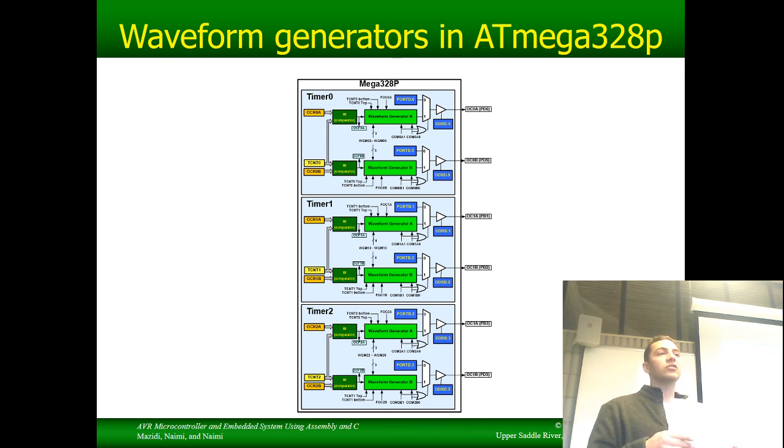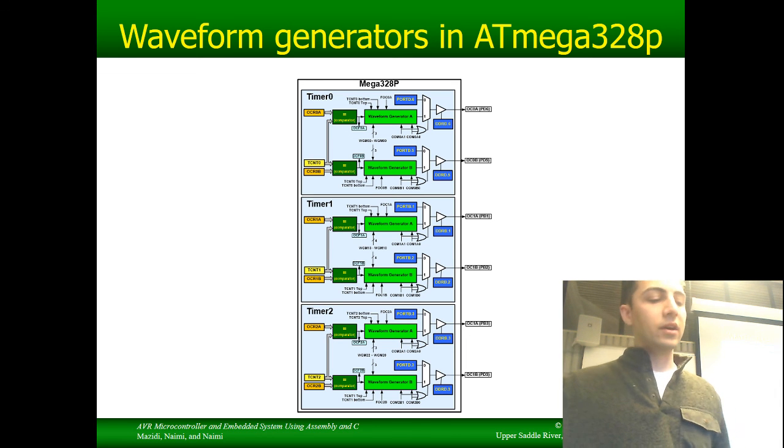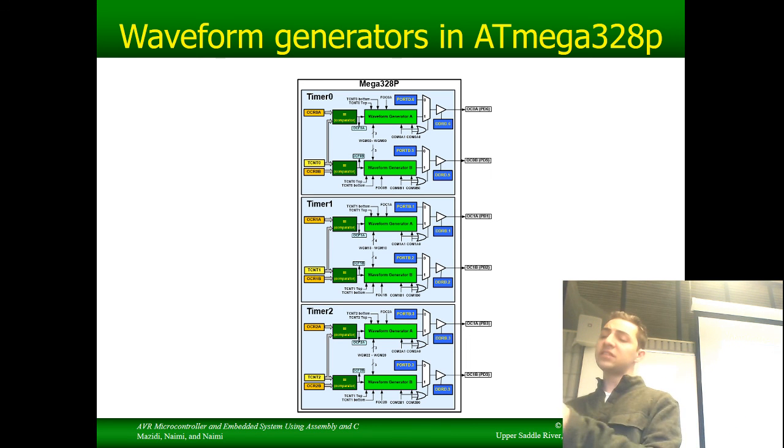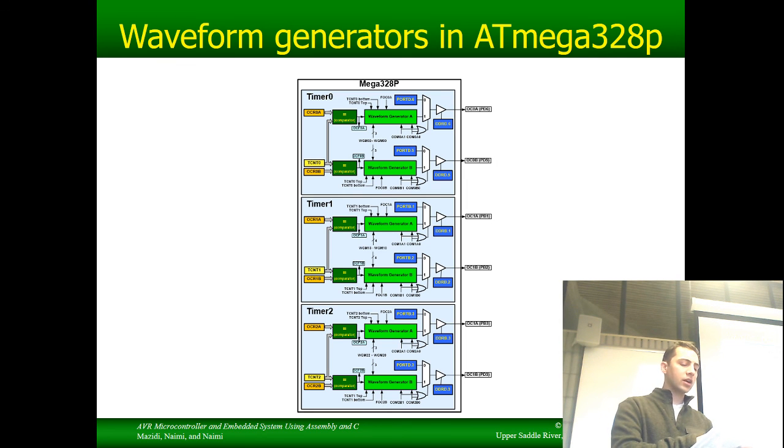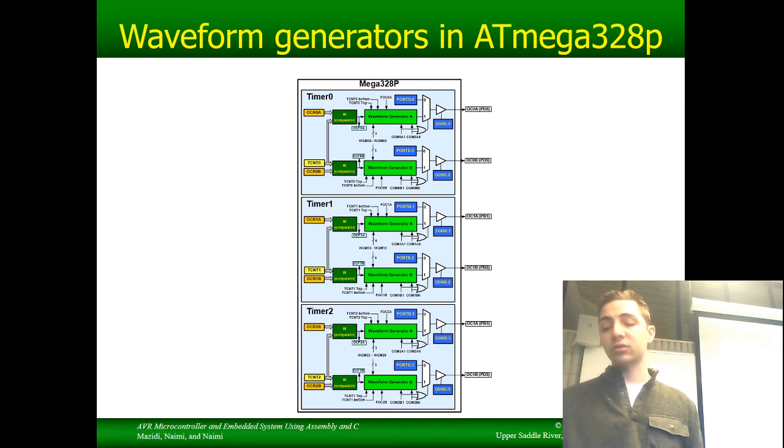So you can write yourself some boilerplate code that says, all right, TCCR0A. I know that I've got COM0A, COM0B, and the waveform generation mode bits in there. I know that in TCCR0B, I've got force output compare, one of the WGM bits, and the clock select bits, or the clock source bits.